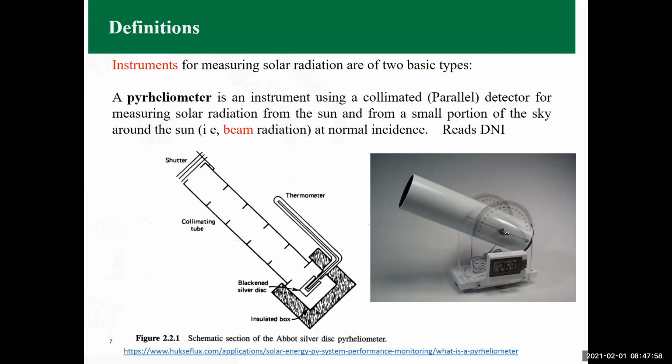You must have seen them in your course, or the lab associated with the heat transfer course, because we rely on thermocouples a lot. What happens in the thermocouples is you have two dissimilar materials. One of them is at higher temperature, the other one is at lower temperature, and the difference of temperature generates what is called the electromotive force, and electricity is being generated. The amount of electromotive force which is generated is proportional to the temperature difference between them.